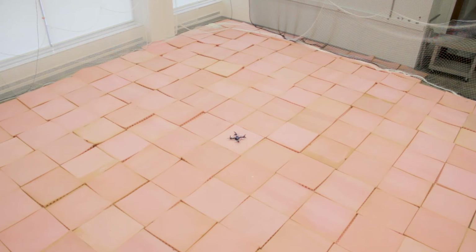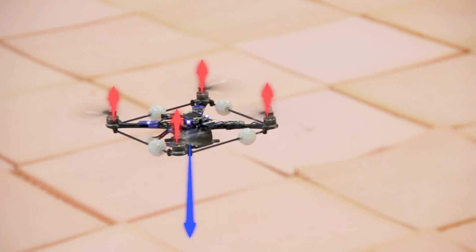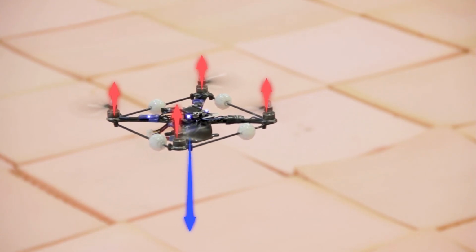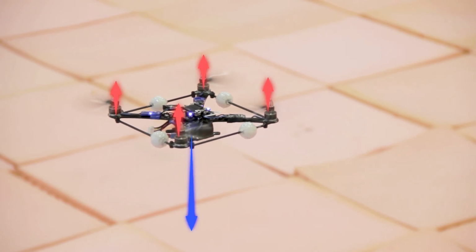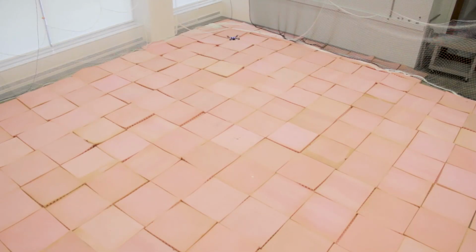Okay, now let's fly. Here, we're going to take off, then perform a figure 8 flight pattern. First, all motors spin up, generate thrust, which creates a force upward. The aircraft then takes off and hovers. Much like the animation before, here we see the forces acting upon the aircraft. Now, we tilt the aircraft to move forward. To start turning, we tilt it sideways to generate the centripetal force. At the same time, we yaw counterclockwise to maintain the force pointing towards the center of the turn. The rest of the pattern follows the same way.